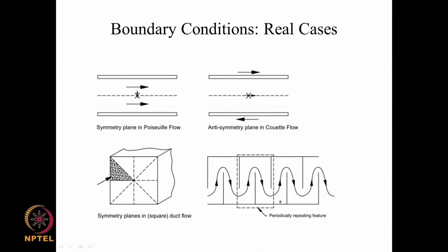So under what kind of conditions you have good flow pattern through this, and what will be the corresponding pressure drop in that, and how is the flow tube arrangement in that going to help us. All those kind of things can be investigated thoroughly by taking a small part of the domain and imposing periodic boundary conditions on this, rather than take all these baffle plates and then increase the number of grid points and increase the complexity of the solution and all that. So you can have these kind of special conditions also that you can bring into play here.